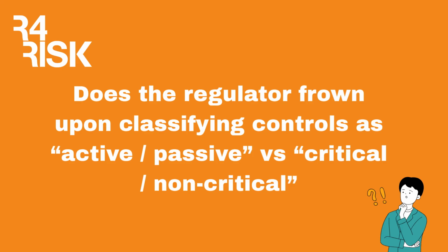an active control that you need people for, or if it's a trip kind of function, they're sort of active controls, whereas of course your passive controls just sort of sit there and do nothing, your pressure safety valves, your bunds and stuff like that. So rather than critical or non-critical, I would see active and passive as a characteristic of those controls. So it would still be a, let's say, bow tie control, but it is an active type bow tie control, or it is a passive type bow tie control.